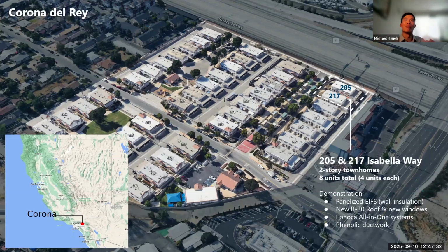And after we had sealed it up and done these insulated metal panels, you no longer have the condensation risk, because even if moist air gets into that attic and contacts the sheathing, that sheathing is now insulated with 6 to 8 inches of polyiso insulation. So we made it an unvented attic, but significantly reduced that condensation risk. Plus, we did that attic air sealing so that there's even less chance of moisture-laden air coming through that ceiling into the attic space. So we dealt with it in two different ways.